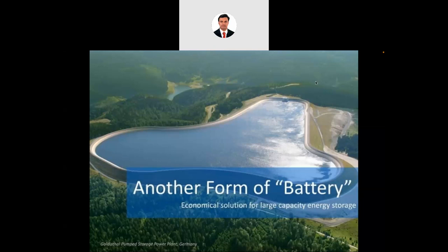So these two storages are very important. Now, we can also store electrical energy in the form of mechanical energy, for example a flywheel. But that storage is only for a very small period of time. We cannot store beyond 10 to 15 minutes. So we cannot store the electrical energy for a large period of time with it. For that, we go towards pumped storage or compressed air storage.